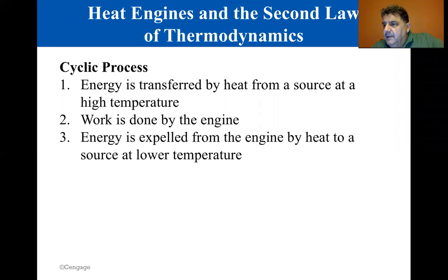Okay. A heat engine takes in energy by heat and partially converts it to other forms, for example, electrical and mechanical energy. In a typical process for producing electricity in a power plant, for instance, coal or some other fuel is burned, and the resulting internal energy is used to convert water to steam. The steam is then directed at the blades of a turbine, setting it rotating. Finally, the mechanical energy associated with this rotation is used to drive an electric generator.